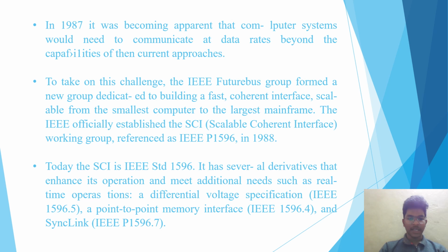Today, the SCI is IEEE Standard 1596. It has several derivatives that enhance its operation and meet additional needs such as real-time operations, a differential voltage specification, IEEE 1596.3, a point-to-point memory interface, IEEE 1596.4, and Synclink, IEEE P1596.7.